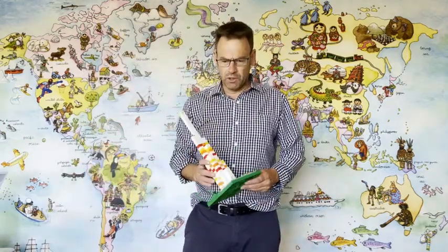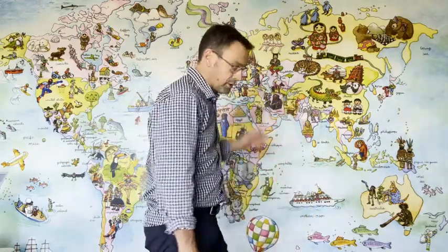That's a great description of the Universal Transverse Mercator projection, and it helps us understand why a metre in your model does not always equate to a metre on the ground. If you want an extreme example of this in action, you need only look at a common map of the world.